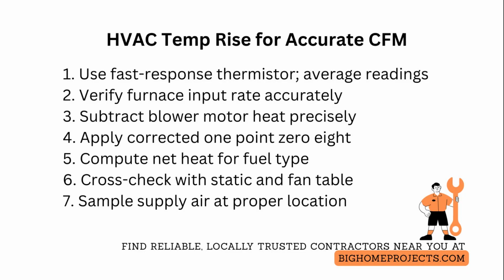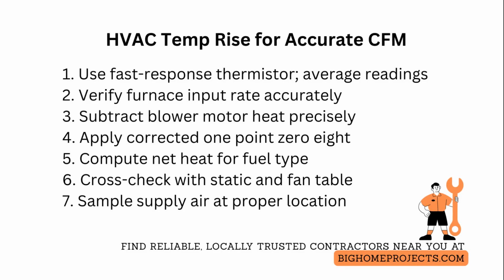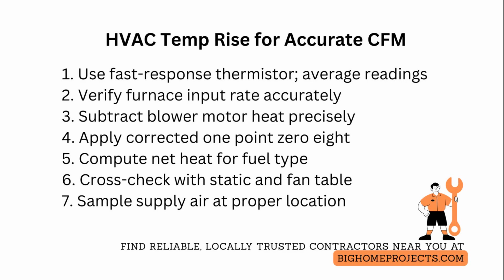Start by taking stable return air and supply air temperatures with a fast response thermistor placed out of line of sight of the heat exchanger to avoid radiant skew. Average several readings across the airstream for both supply and return to lock in a reliable temperature differential.